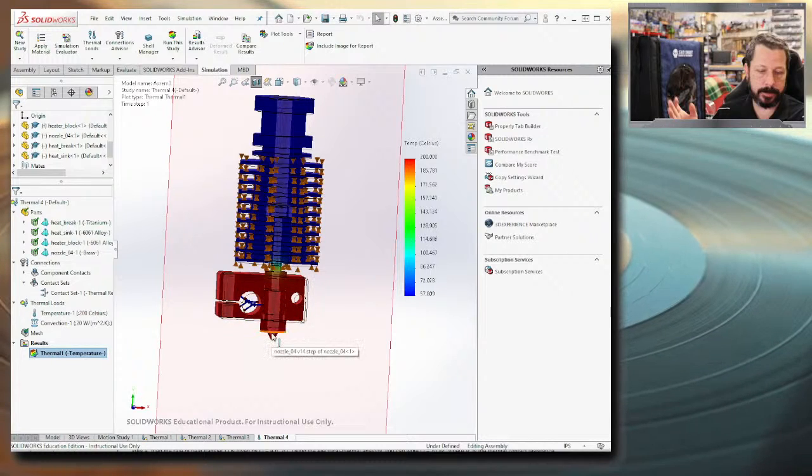And so you usually want to do that if you're trying to print with a really large nozzle or print really fast. The faster printing speeds mean you have to extrude more filament, and in order to do that, you have to melt it faster. And so the faster you want to go, the larger nozzle you want to use. Basically, the more volumetric flow rate you need of filament coming out of the nozzle, the more heat you're going to need to be able to get it to the point to where it can actually be pushed out of the nozzle. And so there are different arrangements of heaters, and some have 2 heaters. And so there's different arrangements to accomplish that.